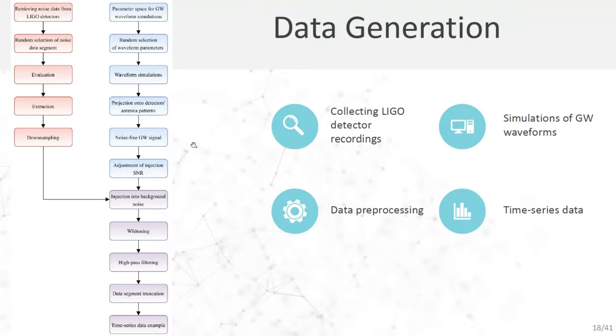And of course, before injection into the background noise, we scaled each signal to obtain data examples with a range of SNR, where the optimal match filter SNR of this one detector data was in the range between 0 and 30 decibels.